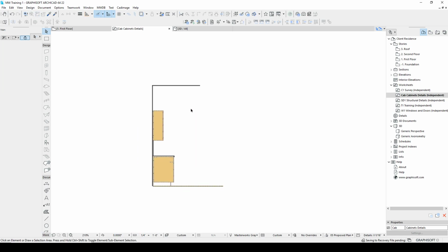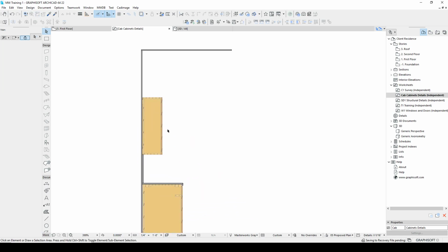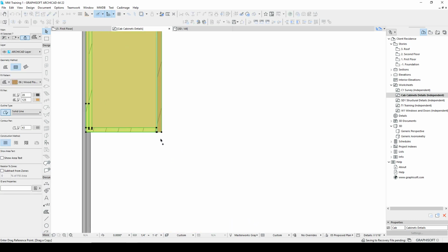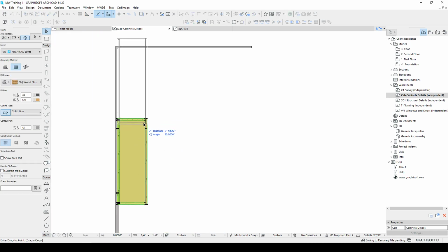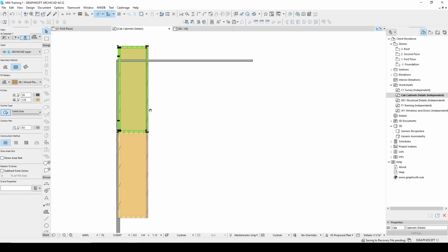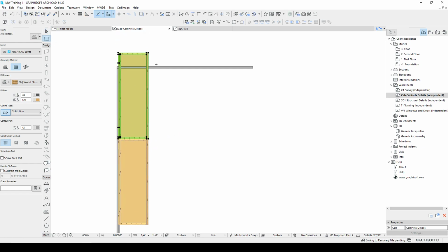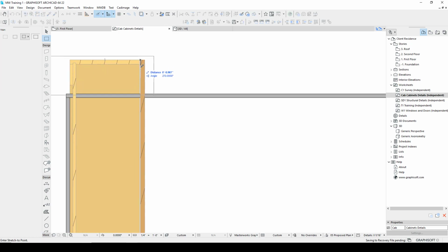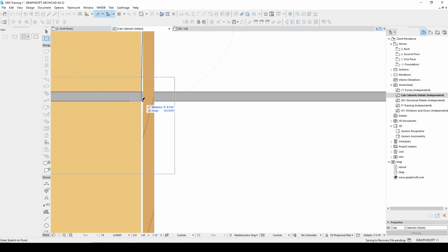Get rid of this line. And then you can say, okay, well, these cabinets are too short. I want to put another cabinet on top for a secondary upper. And I can plop that on top. Come up here. Stretch that with the F8. And I'm going to come down 3 inches.